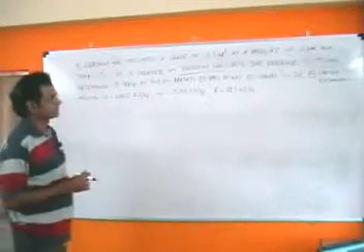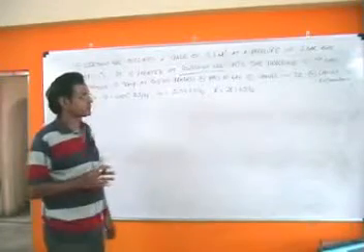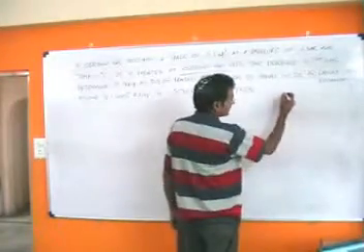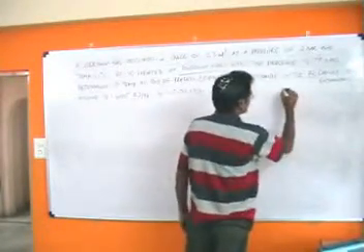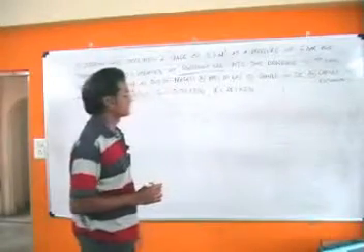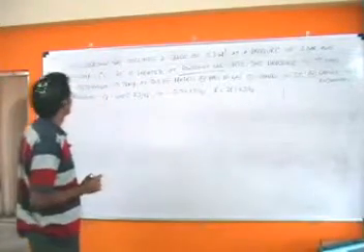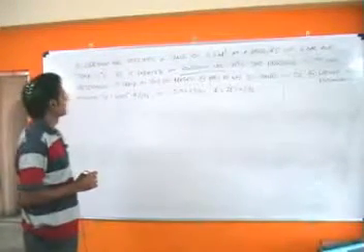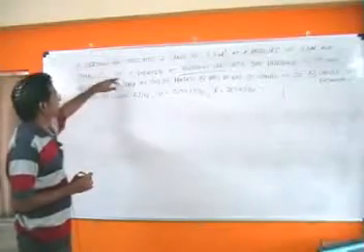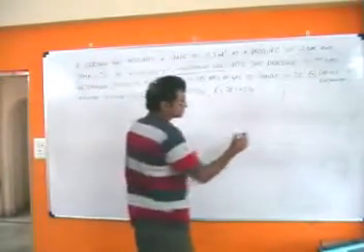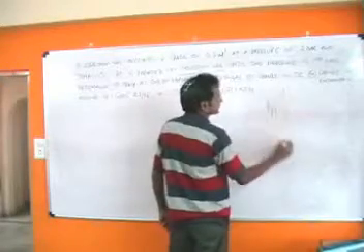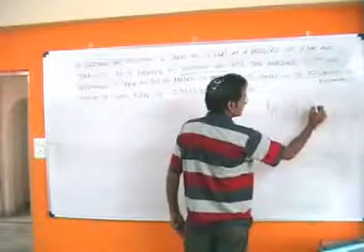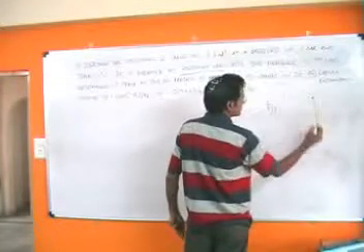So basically, in order to do problems in thermodynamics, the first and foremost thing you need to do is draw a PV diagram and plot all the values given in the problem, so that it is easier for you to understand. Let us now draw a PV diagram for this problem. The gas occupies 0.3 meter cube at a pressure of 2 bar and a temperature of 77 degrees centigrade, and it is heated at constant volume. Since we have pressure on the y-axis and volume on the x-axis, and a constant volume process, our graph goes from here to here.